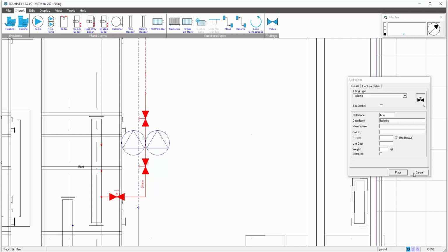If I want to insert a commissioning set and other valves on my return, quite simple, just select another selection from the listing, selecting the commissioning set. I'll place this on the high level pipe work. It will choose the pipe run that you're looking at. That then places the commissioning set at high level. And again, I can put my isolating valves either side of that commissioning set.